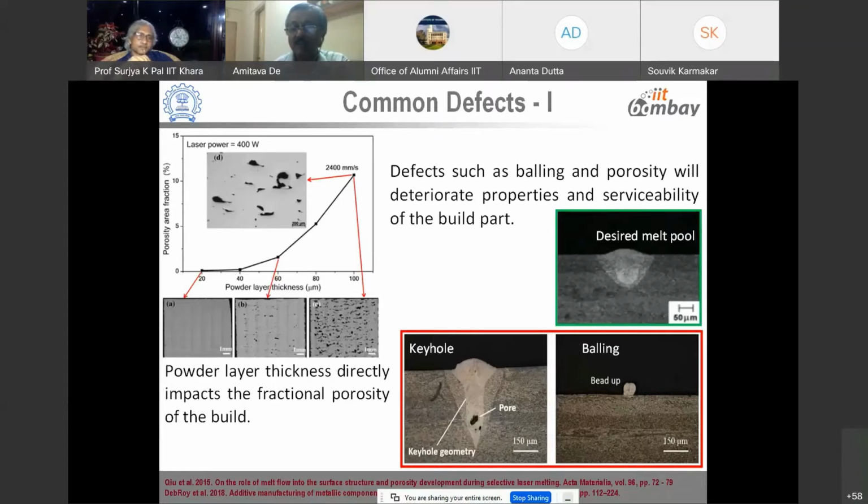So the top surface powders and some powders inside won't be heated up in the same manner. As a result, there is balling, or some kind of spherical shape that comes up. I don't want to go into the details of that, but this is very standard in powder-based processes because of differential heating and melting along the layers of the powders.